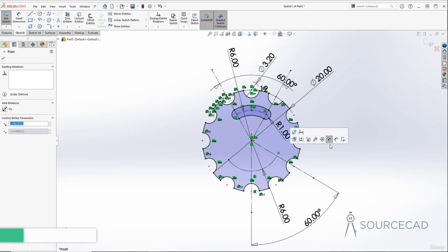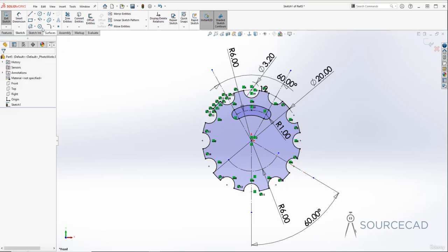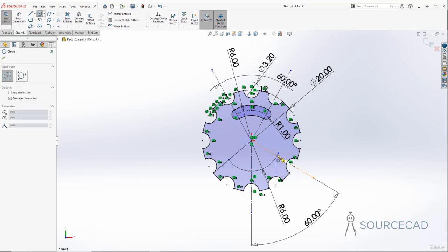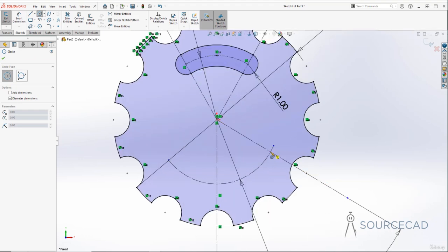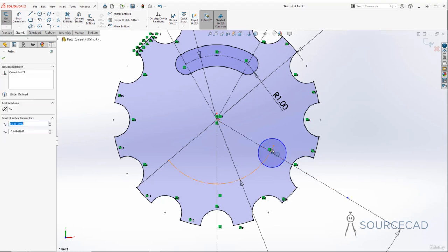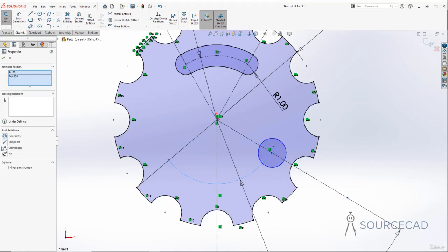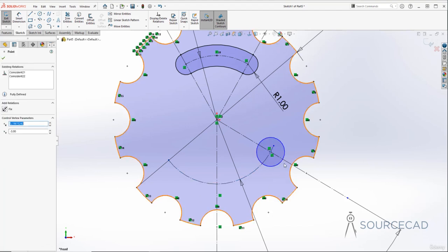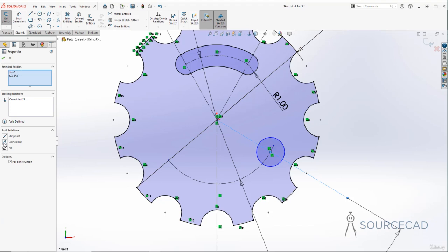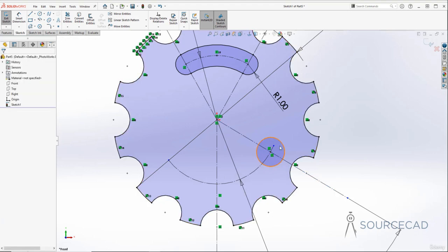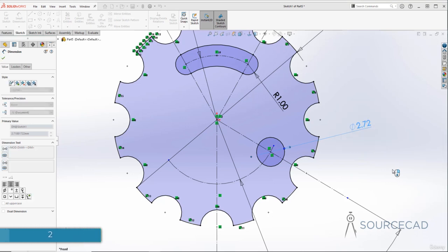I just need to increase its length a little bit further so that we get this intersection point, and right at the point of intersection I will now add another circle here. So I'll just add it like this, and of course this is not at the point of intersection, so I'll make sure that it is coincident on this, and also I'll ensure that this center is coincident on this one. This will ensure that it is actually coincident on both, which makes it exactly here at the intersection point. There we are. Now I'll add the dimension here. So its diameter is 2 unit.